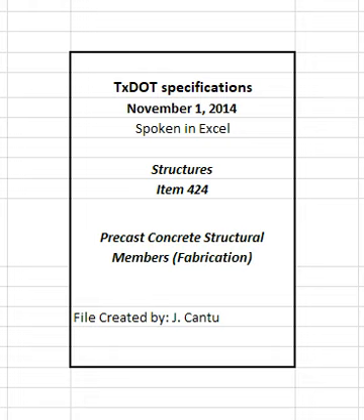4.2.3 Placing reinforcing steel. Place reinforcing steel in accordance with Item 440, Reinforcement for Concrete. Reinforcing steel projection outside of the member must not be more than 1/2 inch or less than 3/4 inch from plan dimension unless otherwise approved. Do not damage sheathing for strand debonding. Do not tie reinforcing steel to debonded strand regions. Weld steel components in accordance with Item 448, Structural Field Welding. Provide welding procedure specifications, WPSs, for approval, and welding personnel certifications per the applicable AWS code.